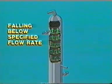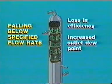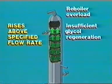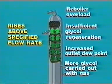Falling below the specified flow rate causes a loss in efficiency and may increase the outlet gas dew point, depending on the design of the trays or packing in the contactor column. If the flow rate rises above the specified range, reboiler overload occurs. When the reboiler is overloaded, insufficient glycol regeneration and increased outlet gas dew point result. The amount of glycol carried out with the dry gas also increases.